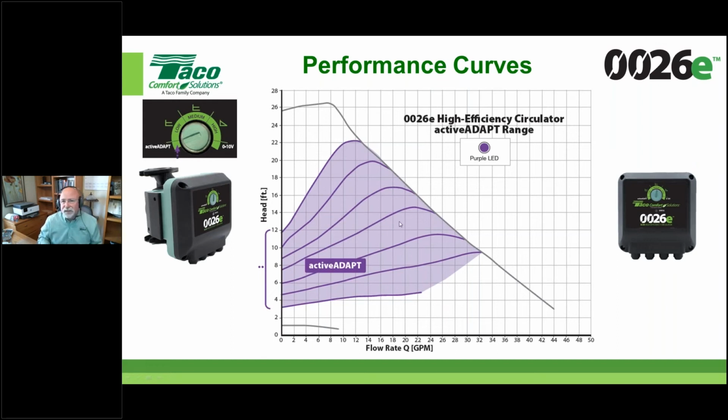bandwidth, because once it's been running for a while and it knows what the hydraulic characteristic of the system looks like with all the valves that have opened and all of them closed in sequence, it'll go through and map out, and it knows it don't ever need to go up here and it don't ever need to go down here. So generally speaking, those are run there. But remember everything that we talked about. Generally speaking, in North America, the adaptable auto modes are the least likely to be the appropriate mode to use